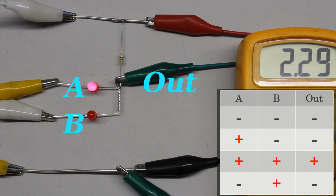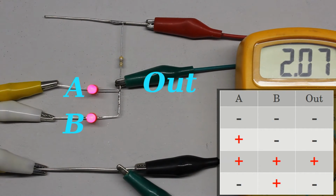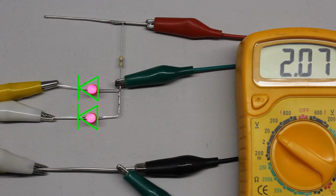The low level at the output terminal differs clearly from ground level due to the voltage drop across forward biased diodes, which depends on the type of diode and is never zero. We can detect 2V by using LEDs.